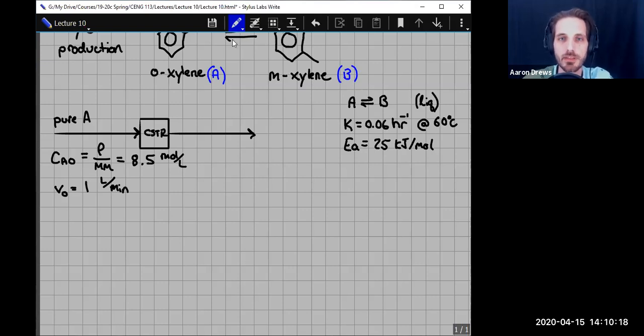The reason we often choose concentrations and volumetric flow rates is a very practical one: we have ways to both measure and control these variables. It's very rare that there's any kind of instrumentation that you could put onto a stream that would tell you the moles coming out. We have ways of getting concentration and volumetric flow rate very easily. And so we're often in a situation where we have to start with those as our measured variables.